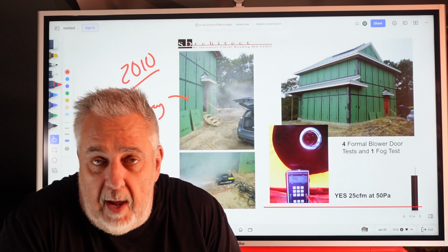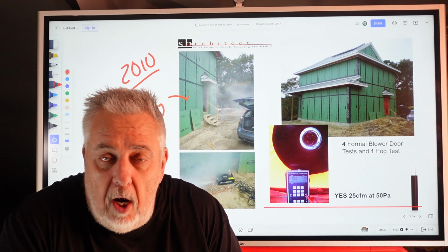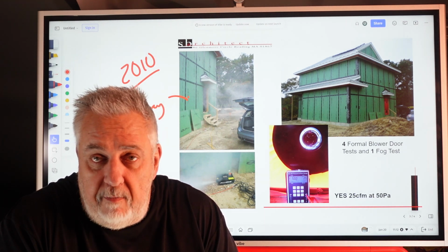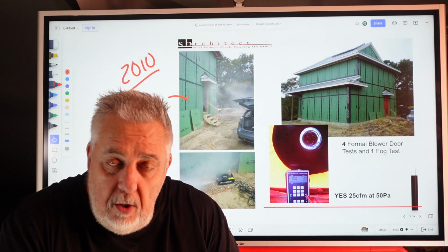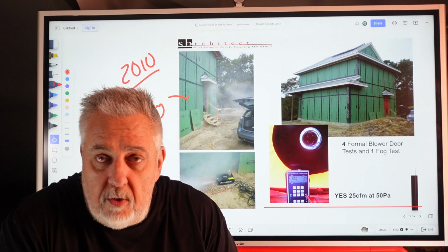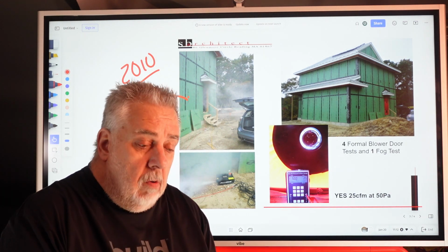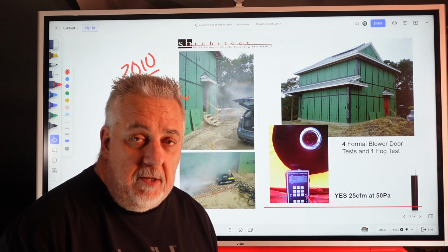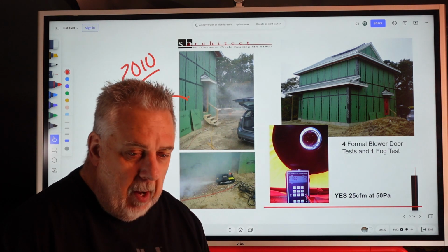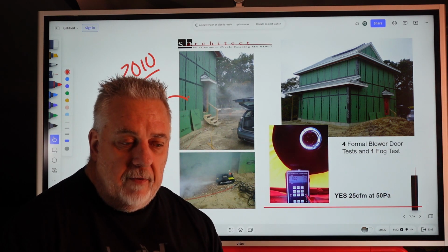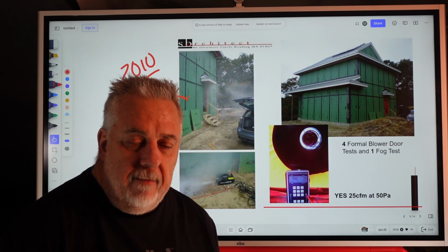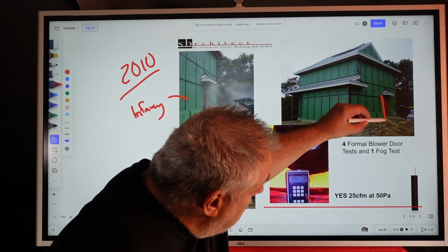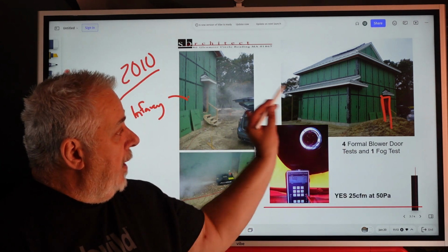At that time, we're still using plywood and taping house wrap and all of this. And now Zip comes along and says, hey, we can give you an integrated weather-resistant barrier already attached to a structural sheathing. And then you just have to tape the joints. So we bought into it, and we're working on the project. Windows are late. And so I look at the builder and I say, hey, I know it might be a little bit of work, but why don't we have the framers do a full Zip coverage over all of the windows. We'll leave one door open. And you can see it there. We'll leave one door open. And we basically blanket it.